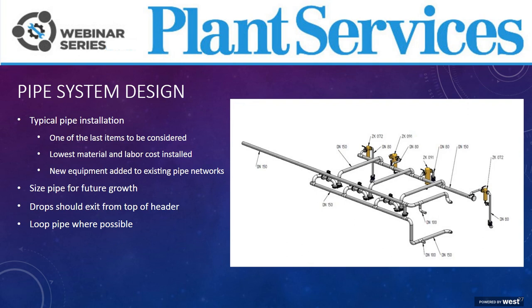System piping can make a huge impact on overall compressed air operation. We don't have enough time today to cover everything to consider, but the highlights would be: don't settle. Put in pipe that won't corrode over time. Size for future growth. Make sure your drops come from the top to ensure that water doesn't get entrained to other points within that system. And finally, loop your pipe where possible to reduce pressure drop.